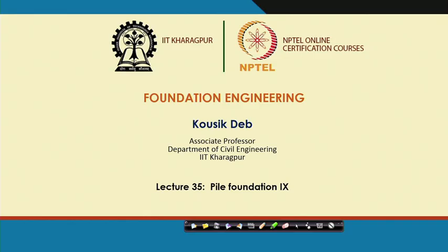So, last class I discussed the pile load test. Now, in this class I will discuss how to get the allowable bearing capacity of a pile from the obtained load versus settlement curve based on the IS code.